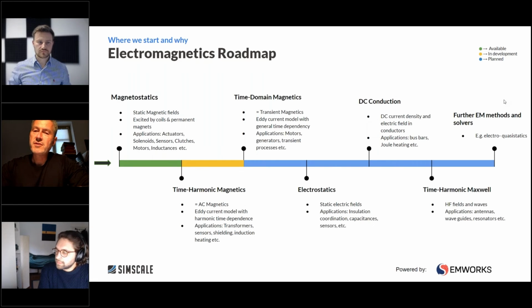If you want to do thermal simulation, combining heat transfer via fluid plus heat transfer via conduction, for instance for simulating the thermal behavior of a complete housing, including electronics, there is already a feature available that allows calculating DC conduction, which automatically gets the heat generated by the ohmic losses, and which then is the thermal source for the thermal calculation.